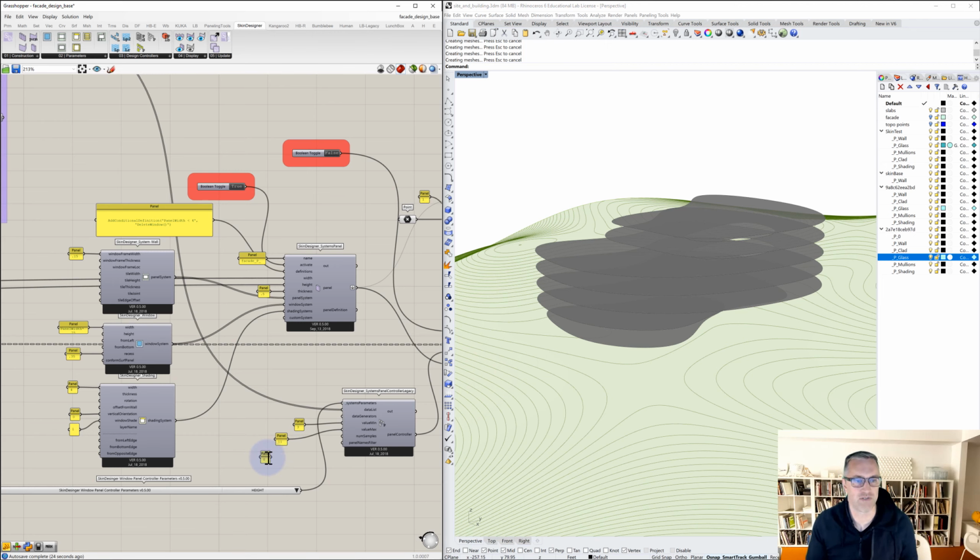This will give us 1 foot increments if we set the panel sampling to 8. If we wanted it in 6-inch increments, we could set this to 16. Where I get 8 is just 11 minus 3. And so each step between the min and the max would be 1 panel type. If we wanted to have a really subtle range, we could increase them. Basically, the number of samples would be the amount of customization. Here, again, remember, this is just the customization of the height of the window.